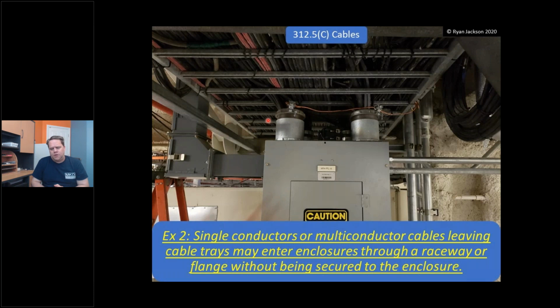We also added an exception in the 2020 NEC that I'm going to talk about really quick, and that is single conductors or multi-conductor cables leaving cable trays can enter enclosures through a raceway or flange without being secured to the enclosure. This is something that we haven't talked about in the code. It probably should have been in the code for 100 years because that's how long we've been doing it. But we leave the cable tray and we enter an enclosure. Very, very common to do this through either a raceway or over here on the left through a flange. Either way, accepted practice, and now it's allowed by the NEC.